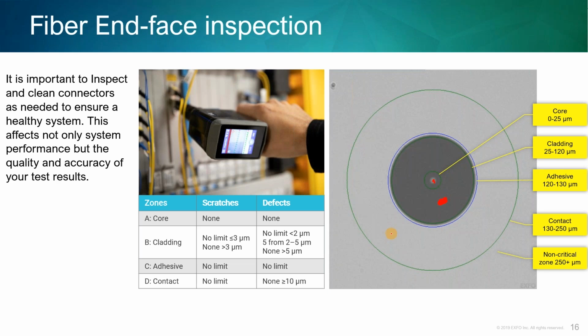For those of you that were technicians, I give this example all the time. When I got a call from the network operations center, said, Kevin, we're taking errors on this circuit pack, on this circuit. I would take my power meter, check the power levels at that circuit pack. And if it was, say, negative 15 dBm, well, that's good light for me in that situation.